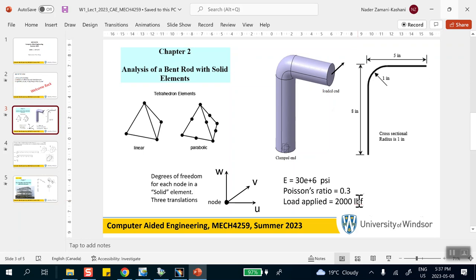Obviously, you must have modeled it in a reasonable way, and if you used a big enough number of elements, the results will be accurate. But in general, one should do a mesh refinement, mesh convergence strategy, to be convinced that whatever color you're getting, whatever numbers you're getting are actually meaningful and reasonable, okay?